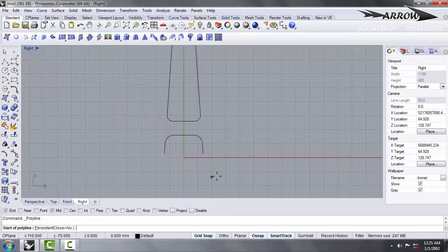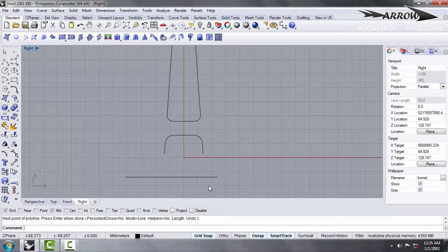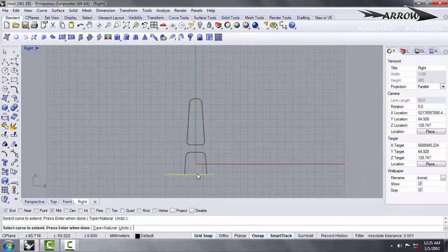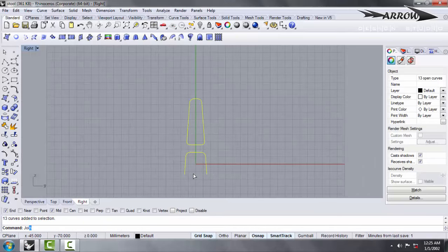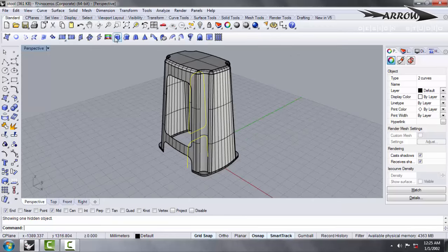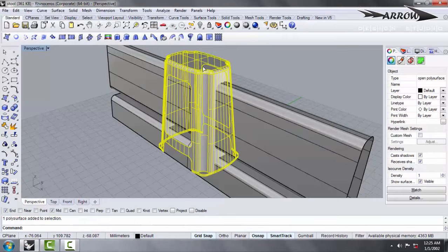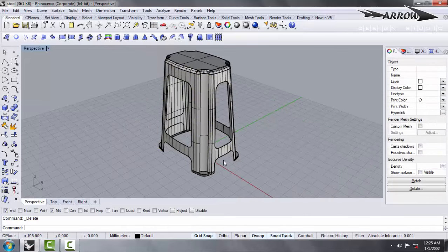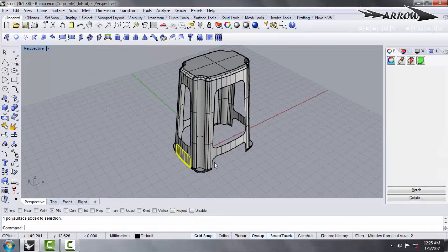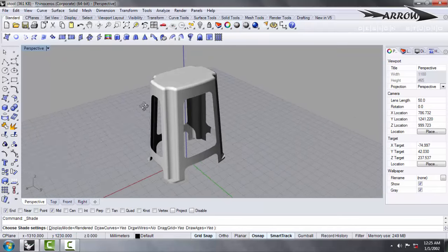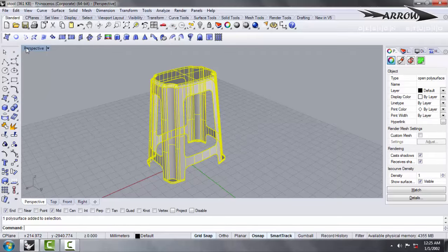and this has to be 20 again. Again I need to do the same thing. I need to just make it extend over here, this point to this point. Okay, control A, join, this has to be joined. Again over here, right click, open it, and say extrude again with both sides, and now trim this by this one and this one as well. So you'll get this has been totally trimmed, and you have got a shape of a stool over here.